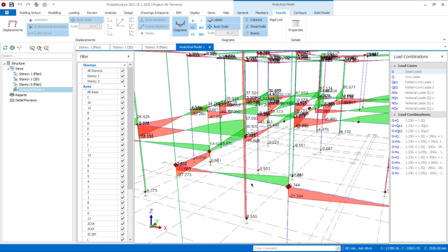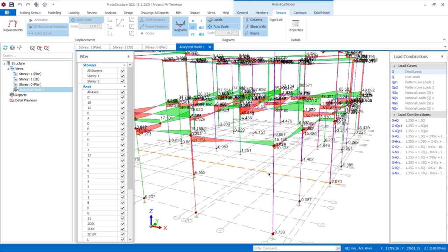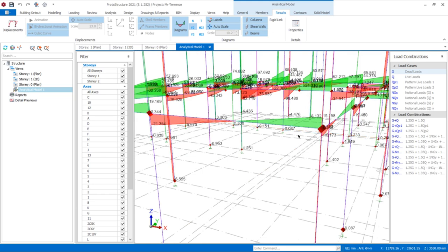That is shear. Now imagine a simply supported beam carrying a heavy load. The highest shear force doesn't occur in the middle. It occurs near the support because that is where the reactions are resisting the applied load. So this explains something you see in construction drawings, and why stirrups are closer together near the support, because that is exactly where shear is highest.